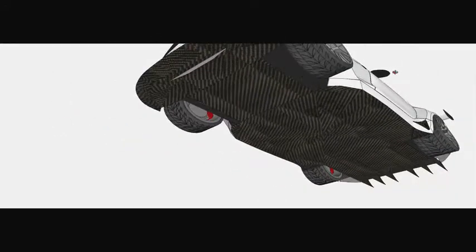The undertray is actually a tray that covers the undersurface of the vehicle, and besides just clearly being for protection purposes, it also allows the vehicle to have less upward force acting on it from the air by covering all the crevices and nooks and crannies created by the positioning of the flooring of the car and the drivetrain and the drive shaft and the differentials and whatnot and the suspension. So basically it creates a flat surface and it minimizes the upward forces to make the car more stable.